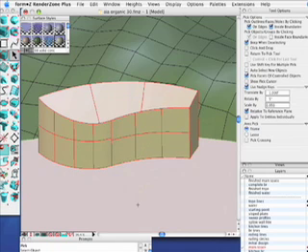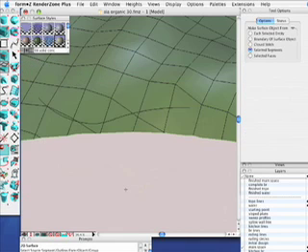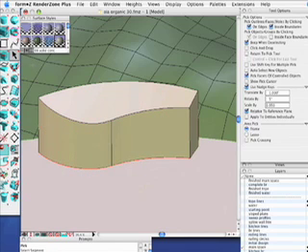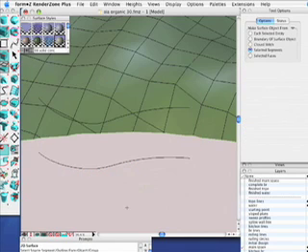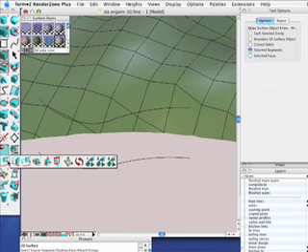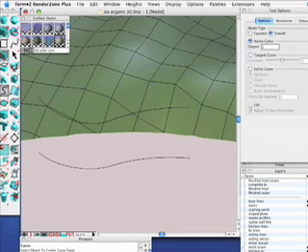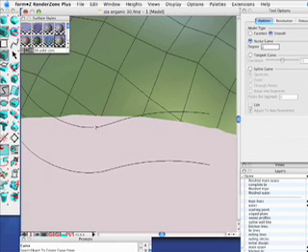Currently, that face is just pretty much vertical. So what I'll do is split away the segments of the top of the front of the face and the bottom. So I'll select those segments, use my derivative tool to make those segments an independent object. I'll do the same thing with the bottom segments. Next, I want to take the bottom segment and make a duplicate of it, so I'm going to drag that segment vertically.